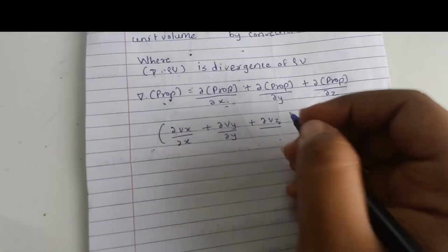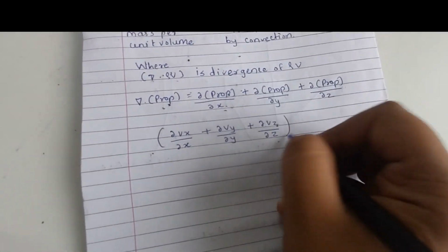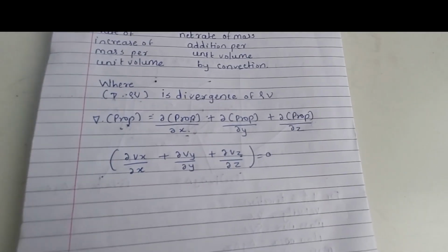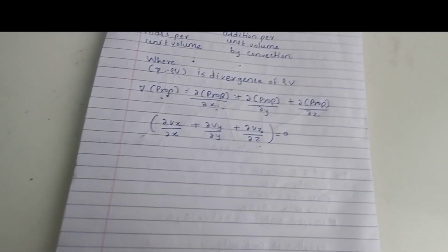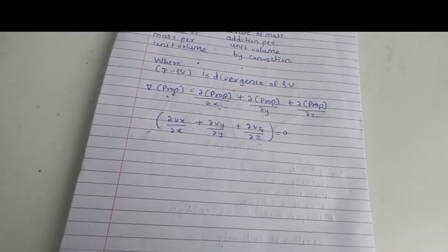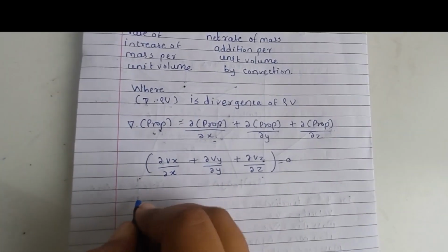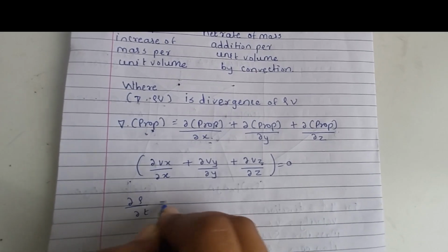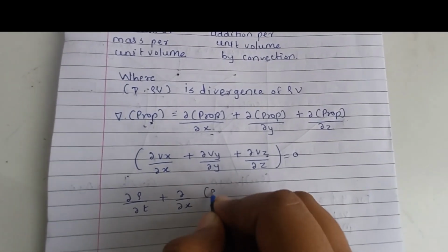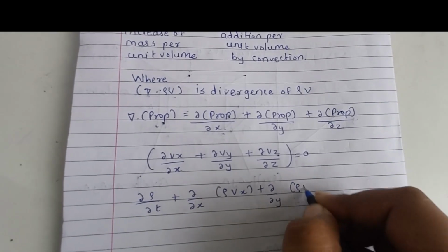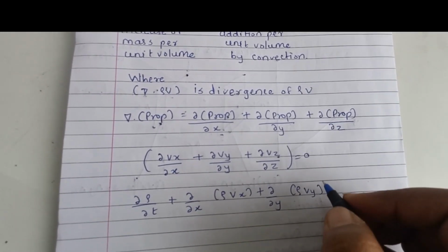And thus here the concept of the del operator comes in, telling us how the fluid is expanding. Negative divergence means water is coming in like a point, while zero divergence means flow is balanced, that is, flow can come in and flow can go out. For incompressible flow, density is constant, and for gases density can change with respect to temperature and pressure.